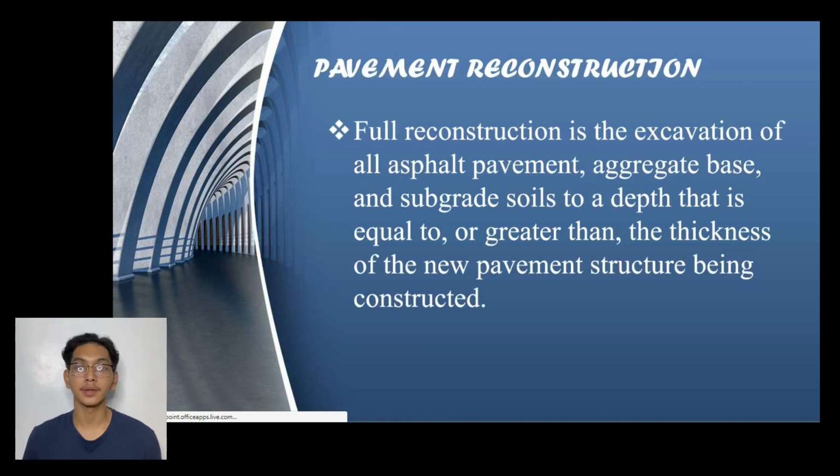The last technique in pavement rehabilitation is called pavement reconstruction. It is considered as the full reconstruction, which is the excavation of all asphalt pavements, aggregate base, and subgrade soils to a depth that is equal to or greater than the thickness of the new pavement structure being constructed.